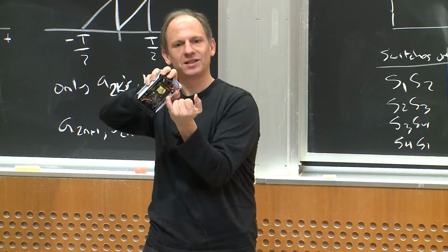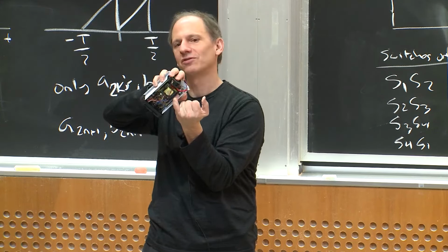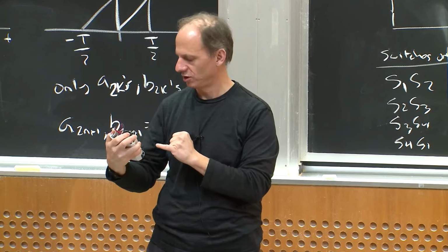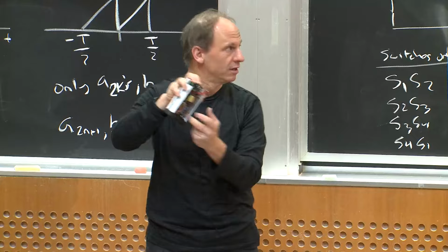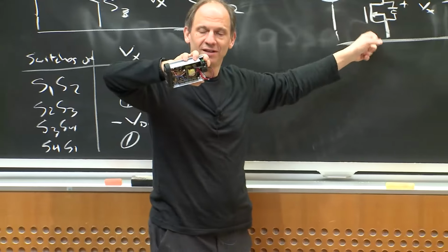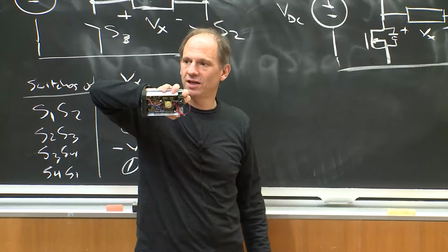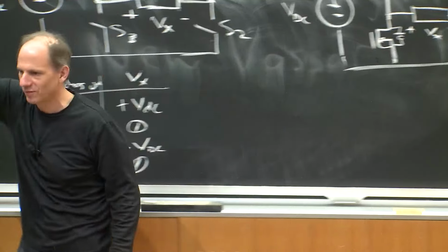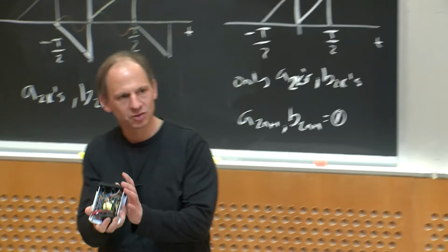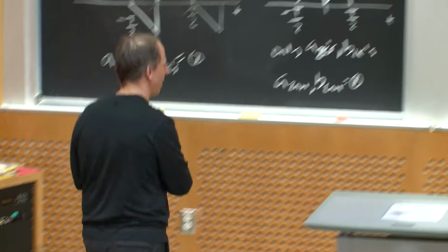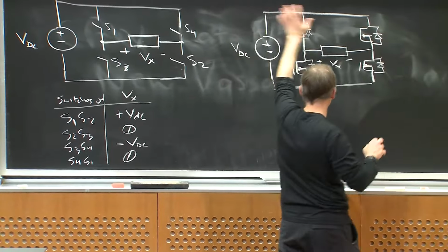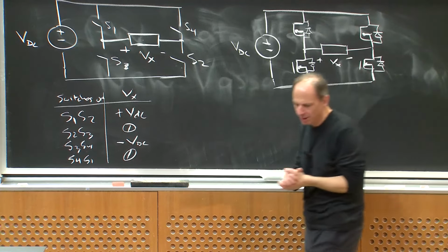That's an isolated DC-to-DC converter. So that takes the 12 volts or 14 volts from your car battery and generates a higher voltage. And then there's 4 more switches, which are the ones here. Those are your 4 MOSFETs. And those are going to generate AC, and it goes to 2 plugs, so you can plug in your toys and play your gaming system or whatever you want. So this is just to illustrate one very simple example of an inverter. And it'll have exactly this structure, right? So we have an isolated DC converter to get us voltage gain, and then this inverter.